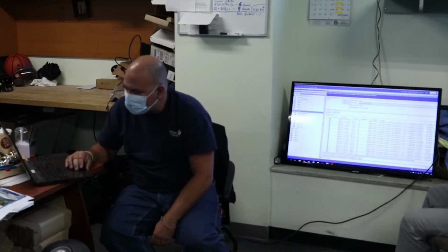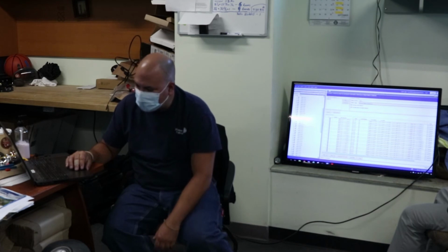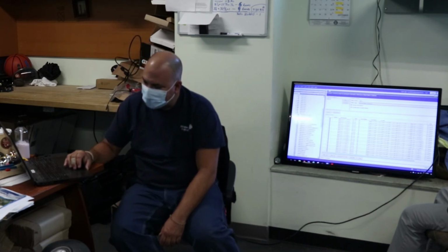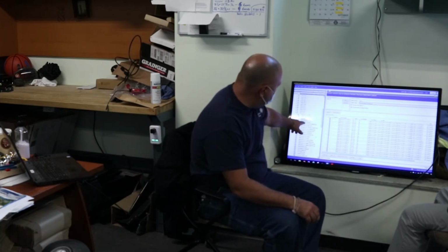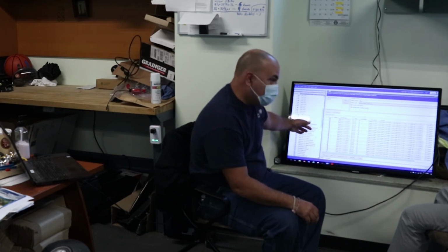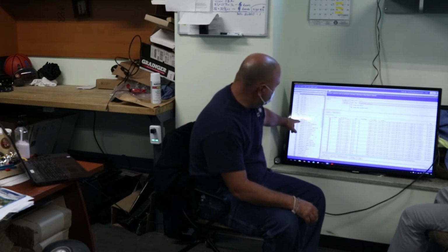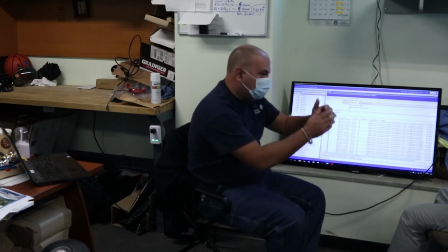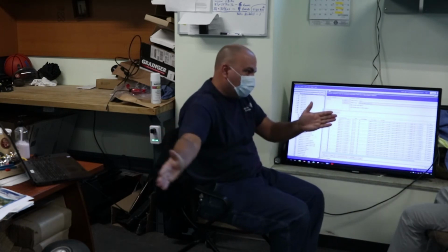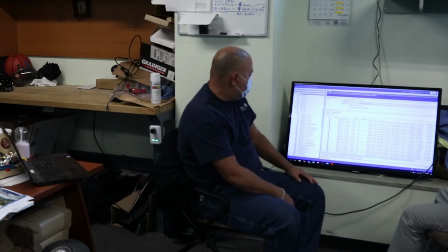All right, so if you look at the tag, I'll just take a random VAV and open it up. So see how it has the heading in front of it? Right, it says NRB VAV 1-3. So by me putting that asterisk there, it'll take everything that comes up with DAT. If I don't put that asterisk there, it won't see it because it'll be looking for all the stuff in front of it first. So it's like an infinity. It basically takes anything from that heading on.